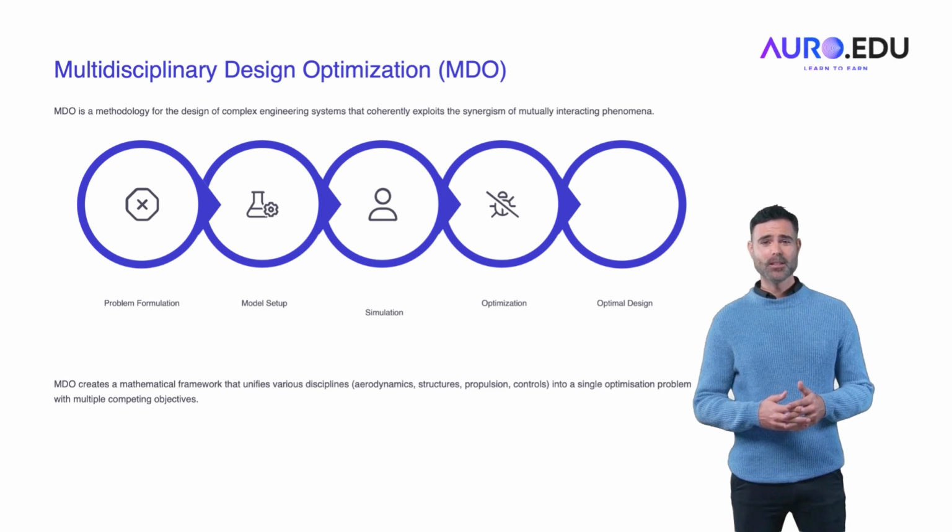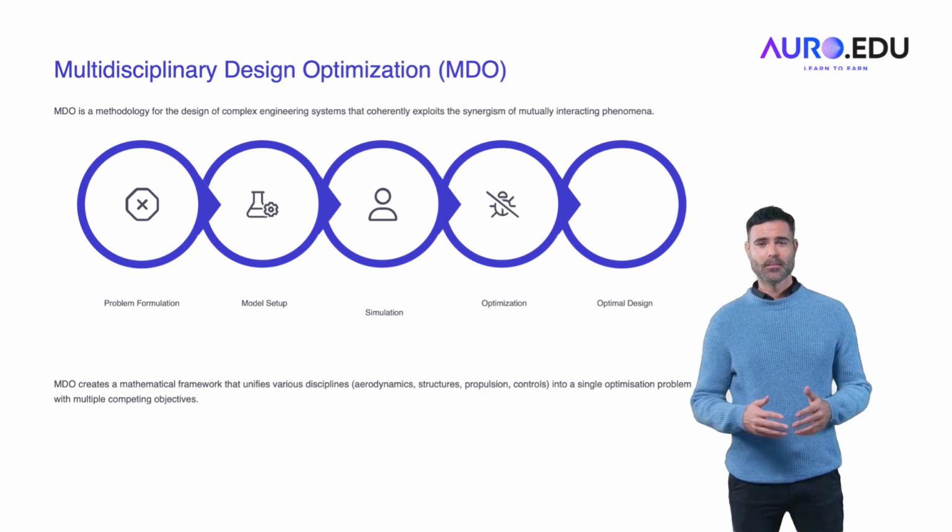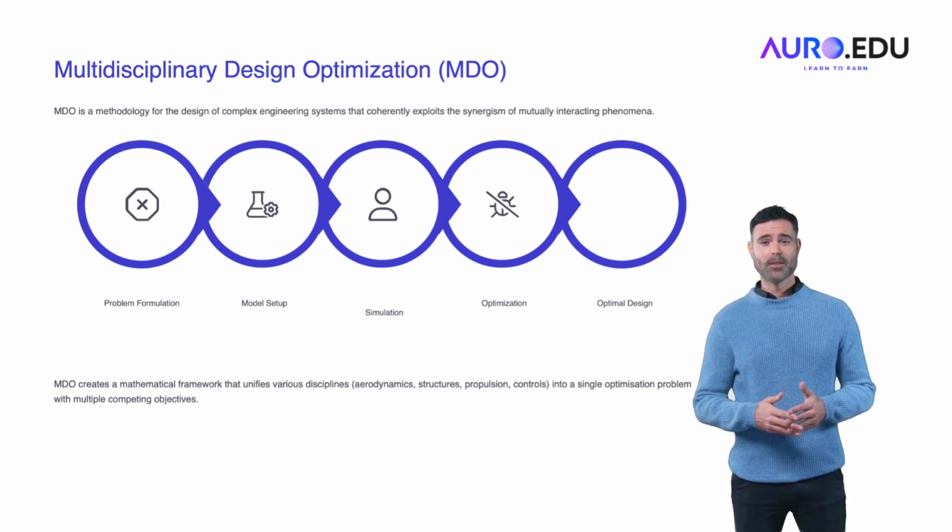Multidisciplinary Design Optimization, MDO. MDO is a key methodology that integrates multiple engineering disciplines into a unified optimization framework. MDO simultaneously considers aerodynamics, structures, propulsion, and control systems to achieve optimal design solutions. The design problem is formulated mathematically with an objective function, e.g., minimizing drag, and constraints, e.g., structural safety and performance requirements. MDO allows for the coherent exploitation of interacting phenomena, helping to balance weight reduction, fuel efficiency, and structural strength